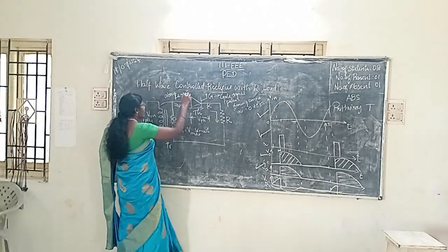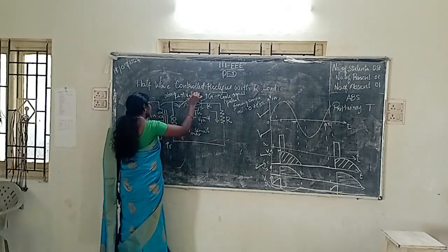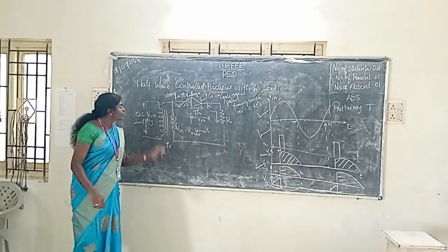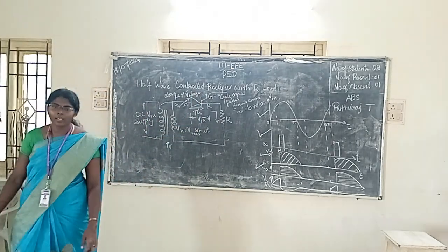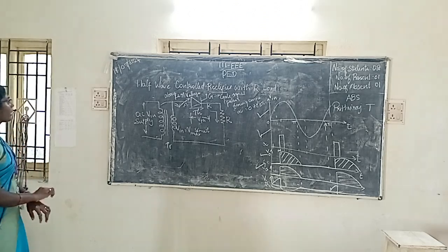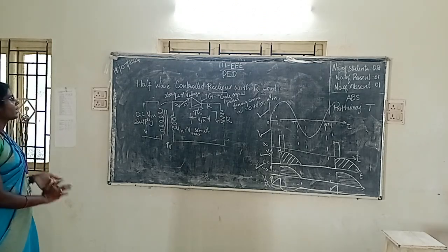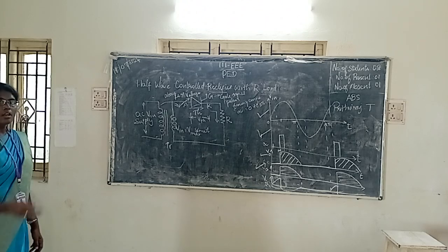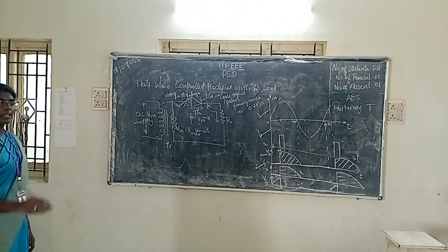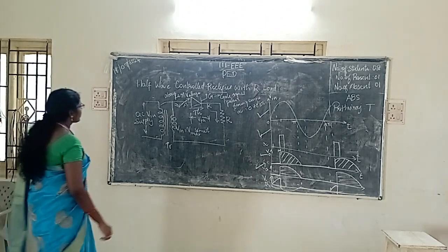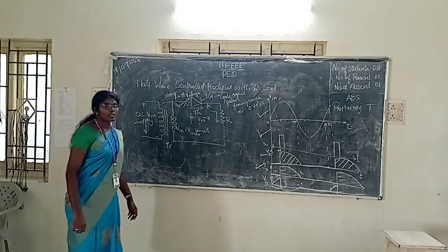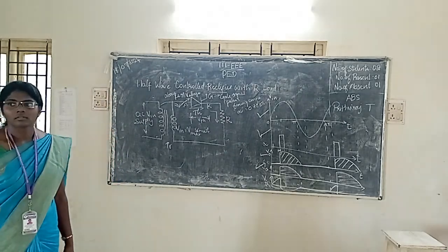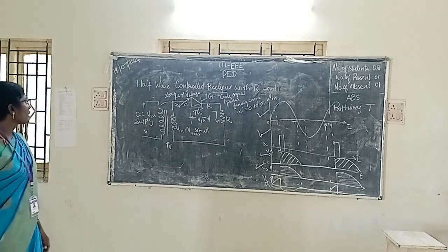Okay, write it down: the input voltage should not be greater than the thyristor's forward and reverse blocking voltage rating. That is the most important point.